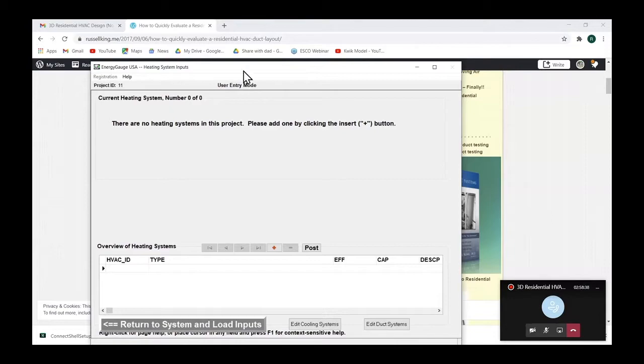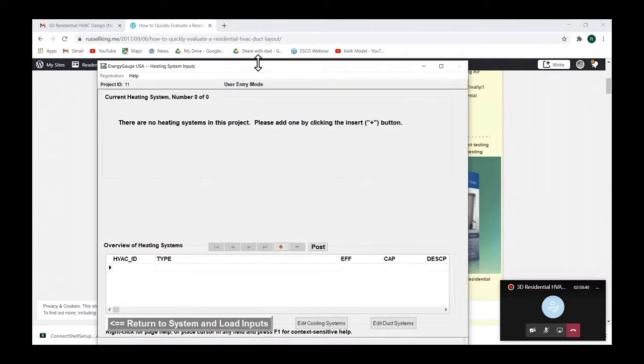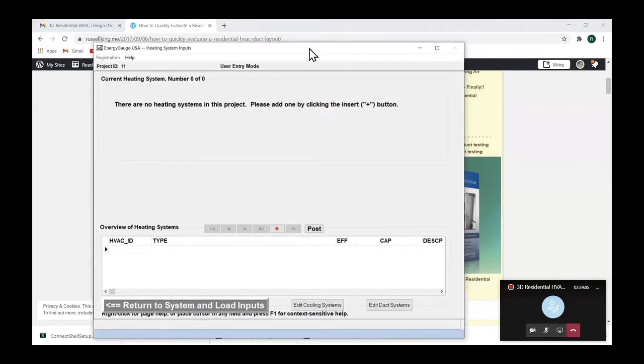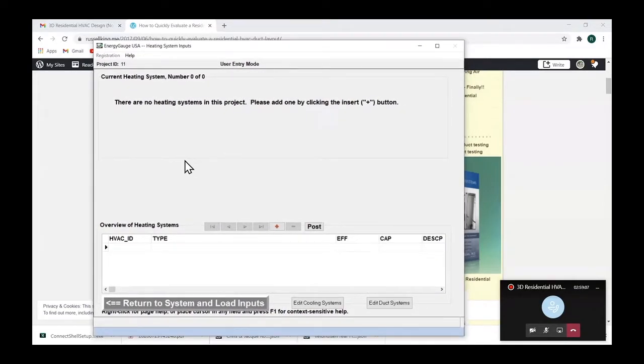And there's also ways around it by looking in Manual J. If you have an actual copy of Manual J and you see these tables, one column is going to be for a certain range of delta T's. The next column over is going to be for a different range of delta T's. And you can look right in that table and say, what's the difference if I have this delta T versus this delta T on that wall? And then you can sort of play around with the numbers that way too. So it's possible. It's doable. It's just not recommended.